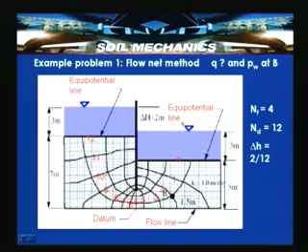So, delta H, the drop occurring, is HL by 12, that is 2 by 12 meters. Now, by knowing the elevation of a particular point, and using total head equal to pressure head plus elevation head, once you draw on graph paper to scale, then by knowing the elevations we will be able to estimate the pore water pressures at any point, and with that estimate the uplift thrust exerted on a particular structure,